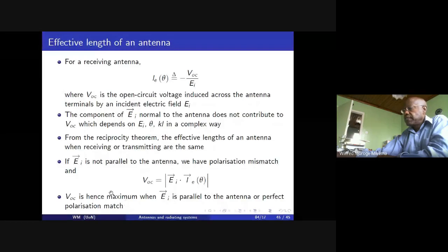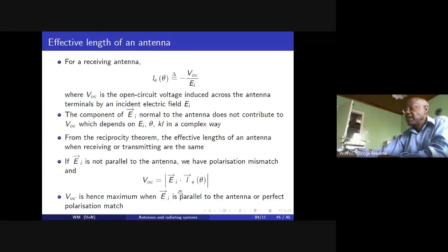And that's why you find that TV antennas are always arranged horizontally, because the polarization of the signal from the broadcasting house is usually along the horizontal plane, that is the XY plane, which is parallel to the Earth's surface. If you look at the police lines in the police stations, you'll see similar dipoles, but these are oriented vertically, because police communication signals are polarized in the vertical direction to avoid interference with the civilian kind of communication.